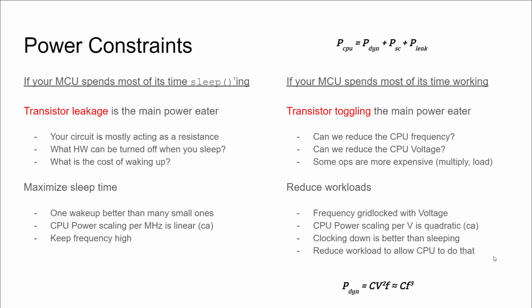You got the MCUs that are always off. The Autopass chip in a car is a great example of this. Every few seconds it wakes up to listen if there's a radio signal from a toll road station nearby. If there is, it will start communicating with that, but more typically it will just go back to sleep because there wasn't any. By this design, the Autopass chip uses so little battery that the chip is likely to be obsolete long before the battery on it is dead. And that's awesome.